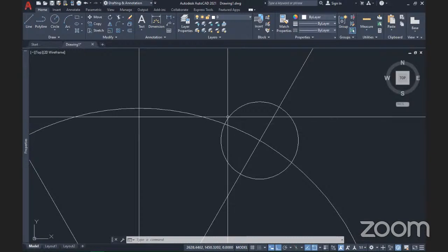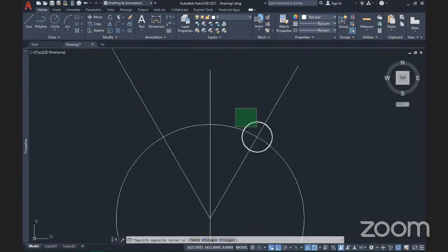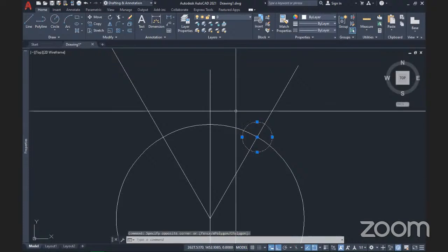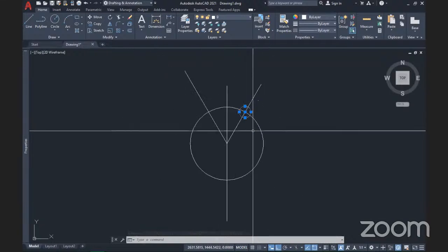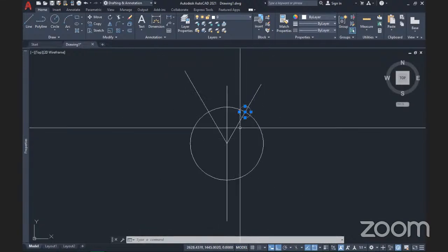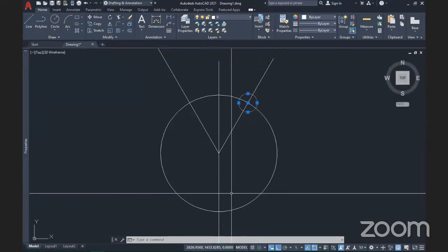Okay, now I want to array this, and I need it to be a circular array. I'll do array classic. Did I show you array classic? I'll do array classic. Array classic is, of course, I did talk about array classic. It's a way of creating arrays using a command. So I'll just type A, Y. And of course, we have array classic right there.